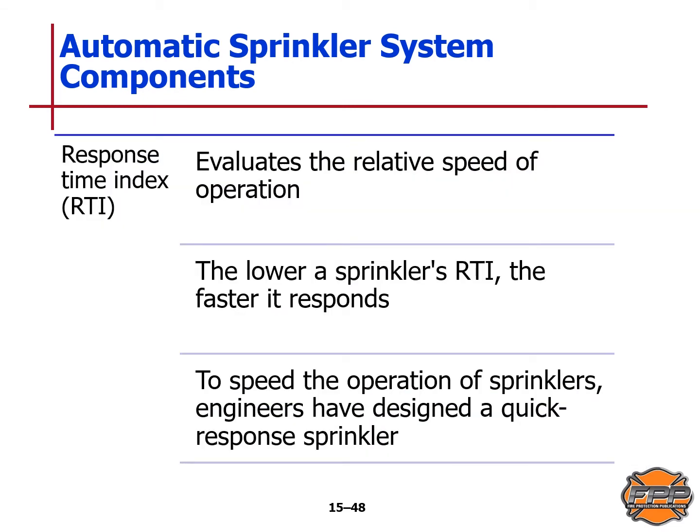Now let's talk about response time index. This evaluates the relative speed of operation. The lower a sprinkler's response time index, the faster it responds. To speed the operation of sprinklers, engineers have designed a quick response sprinkler.